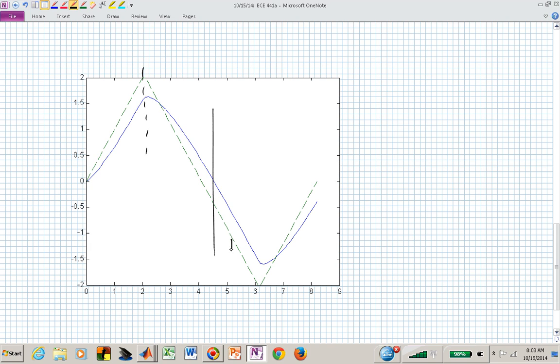And you might be saying, here is where I will define my steady state error. And now you have to measure that distance. That's the distance between the dashed line, your reference, and where you are actually going, which is the blue curve. That's the steady state error in this example. Is that clear?